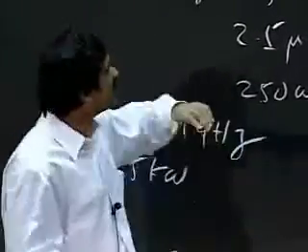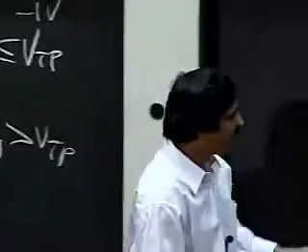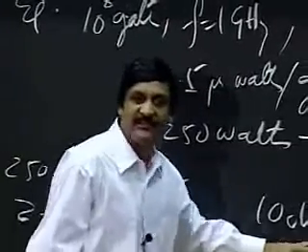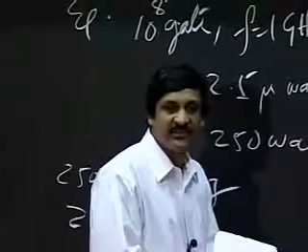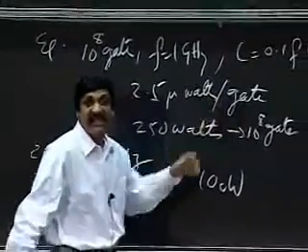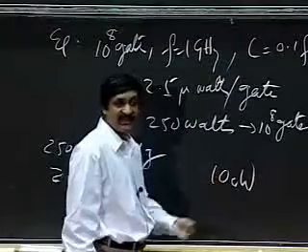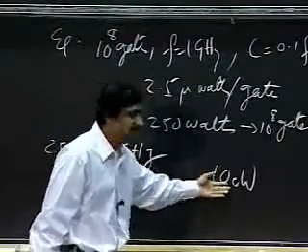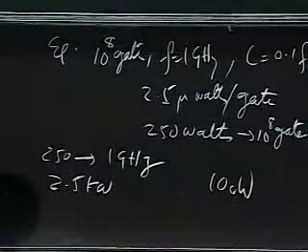It's equivalent to turning off both the PMOS and NMOS transistors. By doing that, you can further cut down the power. This is called idling a function unit. Idle a function unit for half the time, and you cut down power by another factor of 2. If we can idle them 75% of the time, we come down to 25 watts. Those are the classes of tricks that people play.